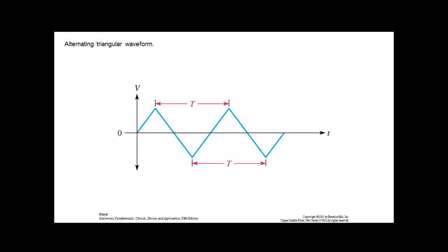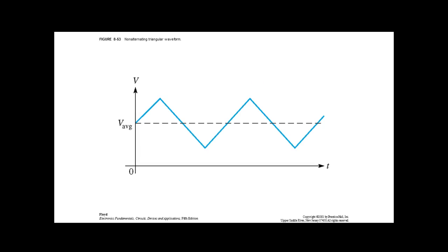So a function generator, the purpose of a function generator, we bring AC in and then we convert it to DC. And what can we do with DC? We can electronically control it, which means we can regenerate an AC. But once I regenerate that AC, it doesn't have to be a sine wave. It could be a triangle wave. It could be a sawtooth, which is one that we'll look at next. But it's going to be AC. So that's some of the waveforms we run into. This is imposing a signal on DC, and we'll talk about this more later, where we can take an AC signal and superimpose it on DC.